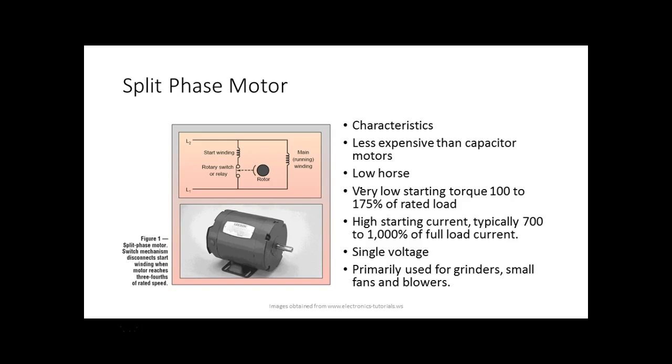If you lower the frequency, the motor's probably going to have to pull more current to produce the same horsepower, right? You understand that? So that's what's on the nameplate. If you look at the nameplate, it's not called full load current. It's called amps. And that's how much current the motor should pull if you're doing what? Running at its rated voltage, at its rated horsepower, and at its rated frequency.